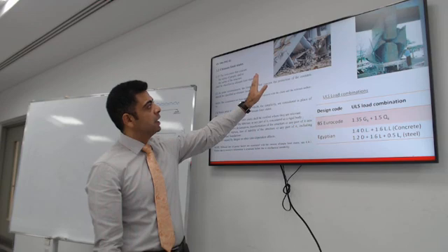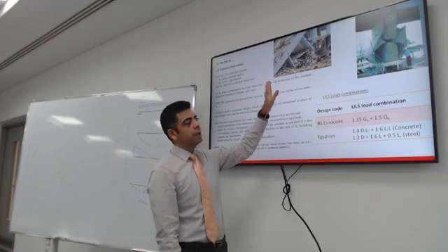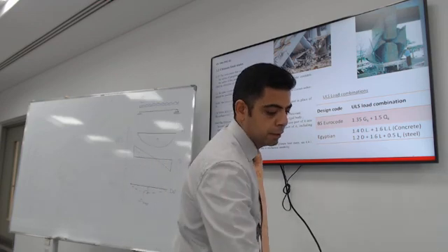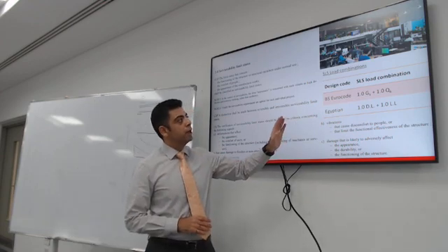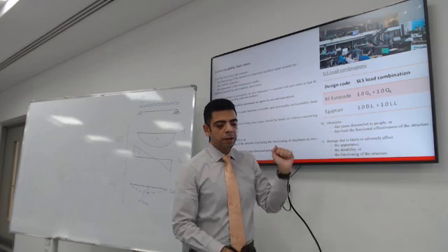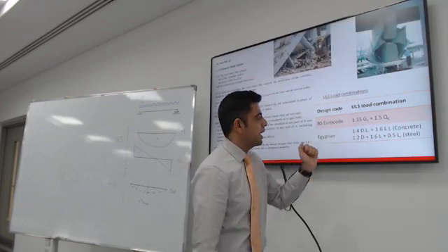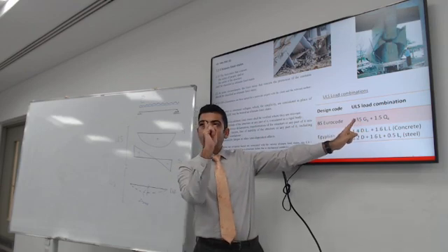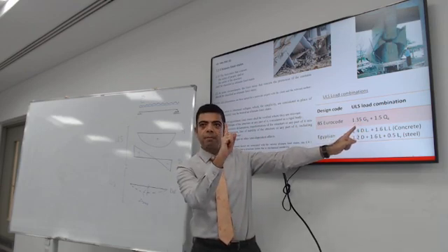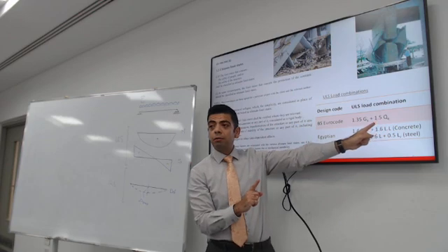The ultimate limit state would avoid the complete collapse of the structure. The service limit state has to do with unfactored loads. So let me just go for a second and notice that you designed the structure not just for the actual amount of dead load and the actual amount of live load.